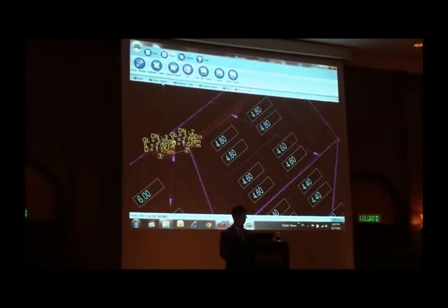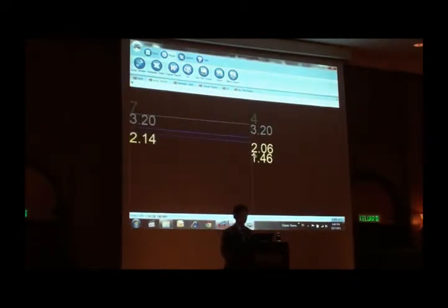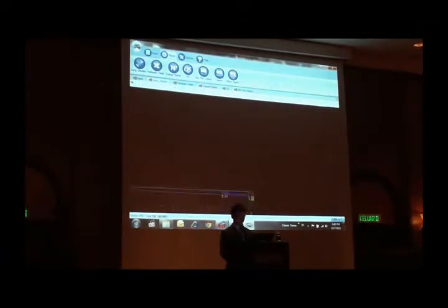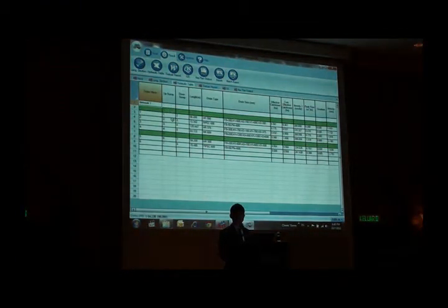For the long section, we provide the long section also now. You can see this is our cascading drain, because the gradient cannot pass, I set 200 gradient and it cannot pass, so it's a cascading drain. Then this is the drop. This twin node number 4 joins into the network, so the program proposes a drop to this node number 4. We also provide the iterative table. This is for submission. This is network number 1. We can do more than one network now. Last time we could not do that. Now it is an improvement.